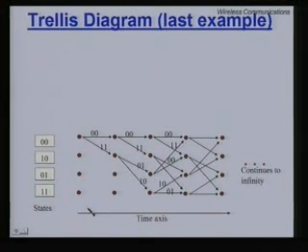Please note our observation as before, coding theory for channel coding deals with introducing structure in the code. So, the general philosophy is, if you have a lot of structure, which is algebraic structure in our case, and noise breaks the structure by changing some ones to zeros and vice versa, then it is easy to identify where the structure was broken and then substitute back and try to do error correction. It is a very layman's version, an intuitive explanation of how coding works, but the structure can be only put up at the expense of adding redundant bits.